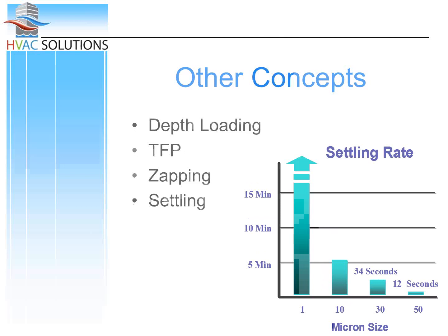Zapping refers to the older electronic air cleaners. You bang on that ductwork a little bit, and it starts to zap. Some people loved it because it made a little noise. They said, hey, my filter's working. I hear it. And then a few seconds later, you smelled it because that arcing, which was the zapping sound, created a little bit of ozone. So then you smelled it. You really knew it was working.